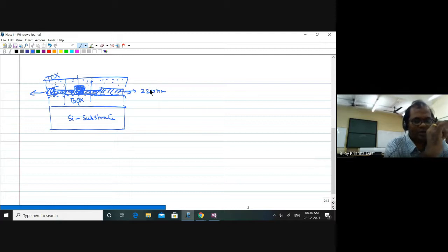What is that? Normally, with smaller dimensions in electronics, for a transmission line, we understand that resistance increases. Resistive loss will be there, and fringing capacitance, all of which are additional problems. Resistance increase means you are encountering a smaller cross section, so electrons do not get enough area to move in.